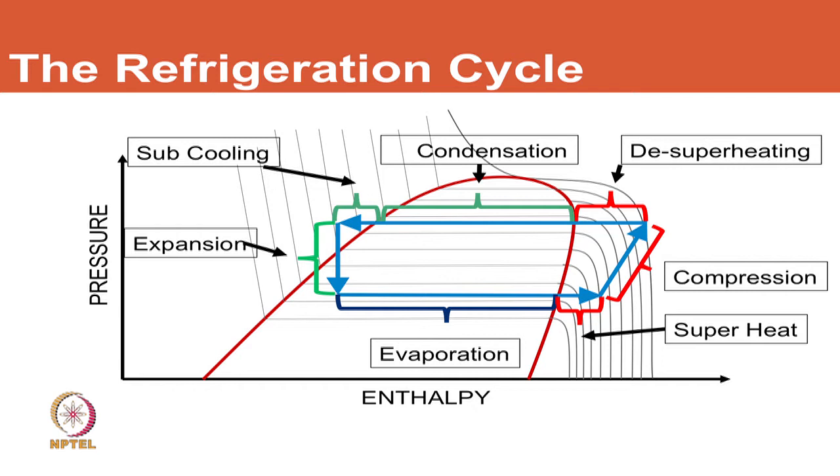Let's take an example of an outdoor air temperature of 35 degrees centigrade. We would like to target a saturation temperature of the refrigerant anywhere between 45 and 55 degrees centigrade, depending on our energy efficiency target. Next is the two-phase phenomenon that happens inside the condenser, but before that happens we have de-superheating.